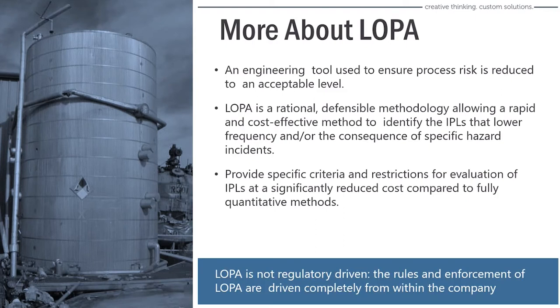What I want to make sure of, though, is that LOPA is not regulatory driven. You won't find the phrase LOPA or layers of protection analysis anywhere in the OSHA PSM standard or in the EPA risk management plan regulation. It is really a best practice, and is driven by a lot of companies trying to go above and beyond what a PHA may entail.